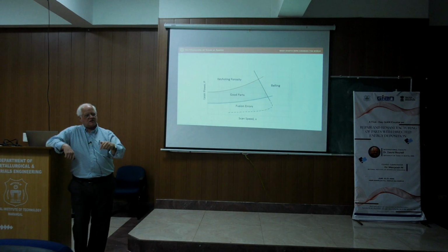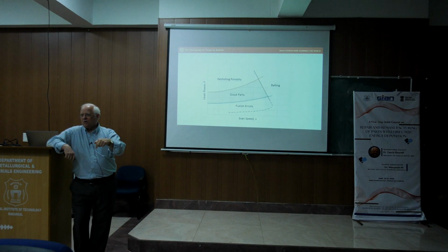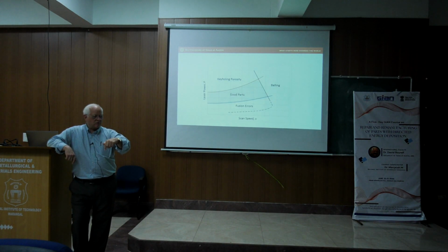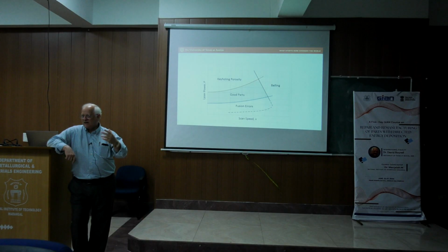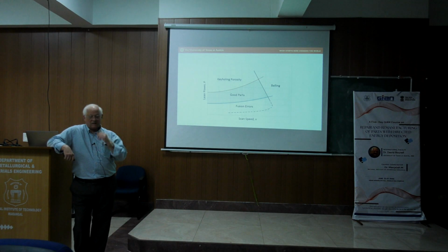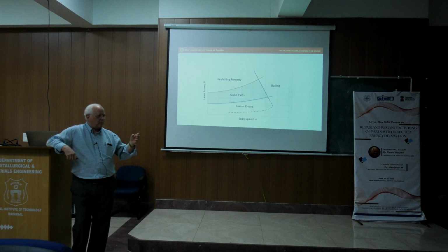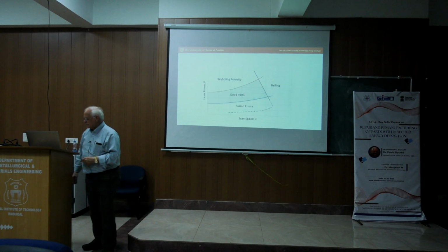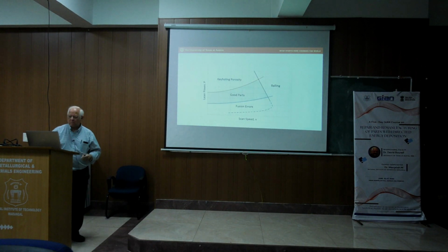But effectively what happens here is there's enough laser power just to melt a tiny bit of pool, and that pool will ball up because there's nothing to restrain it. It'll ball up into a sphere and solidify. Then the laser beam or energy source moves down a little further and that repeats, so you can produce this line of spheres, which is a balling effect. But it's a different mechanism from the Rayleigh instabilities that we have up here at high scan speeds. Anyway, I mentioned that just in passing.